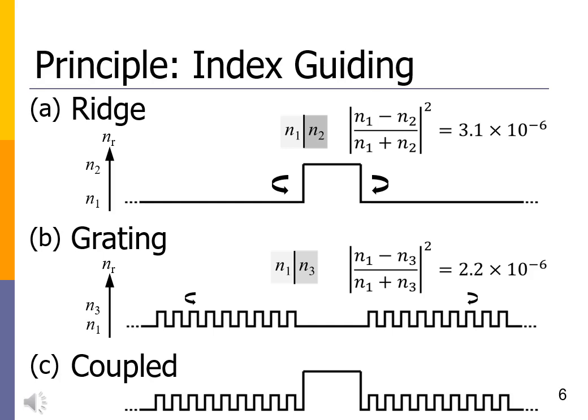Both the ridge structure and diffraction gratings make the light waves resonate. In general, the wavelengths of the resonant modes of the ridge structure are different from the wavelengths of the resonant modes of the diffraction gratings. We design the waveguide so that the wavelength of the fundamental horizontal transverse mode of the ridge structure and that of the diffraction gratings may agree with each other. As a result, only the fundamental horizontal transverse mode is confined to the waveguide with optical gain.